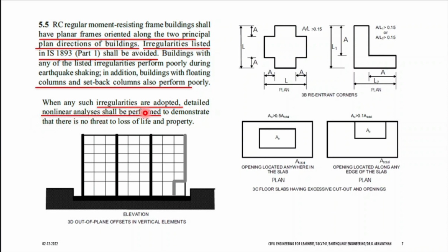So, in the BE syllabus, you do linear analysis. There are two types of behavior for each and every material. One is linear behavior and another one is non-linear behavior. What do you mean by linear behavior is, if you give a force to a member, take this as a column. If you apply a force to the column, remove the force, the column will come to its original place. This is called linear behavior, and if you add 1 kg, 1 mm of deflection will be there. 2 kg, 3 kg like that, you can constantly increase force, deflection will be constantly equal. This is called linear behavior. Linear is a straight line.